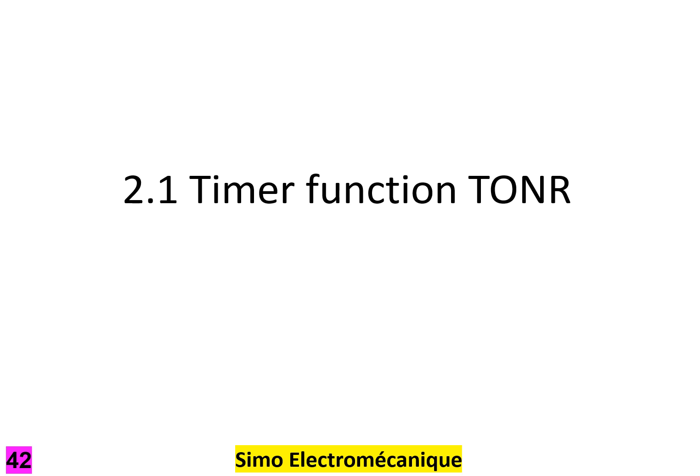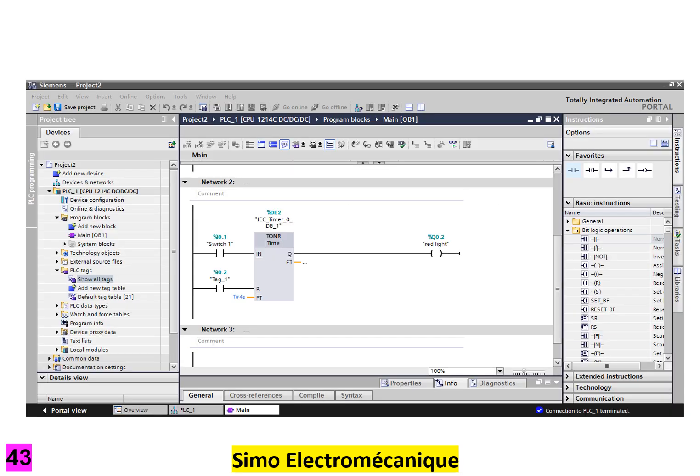Timer function TONR, T-O-N-R. The TONR timer has some important differences. Its timer only runs when the input IN is on. If IN is switched off during timing, the timer is paused. In effect, it records the total time that input IN is on. The other timers, TP, TON and TOF, disregard changes to IN once triggered.